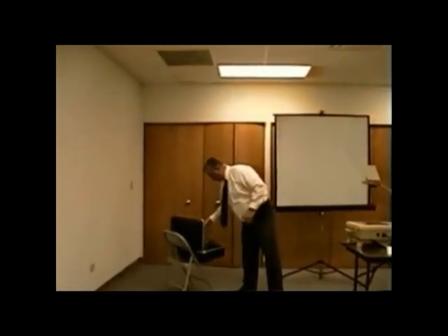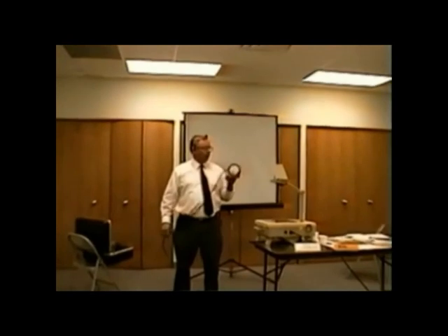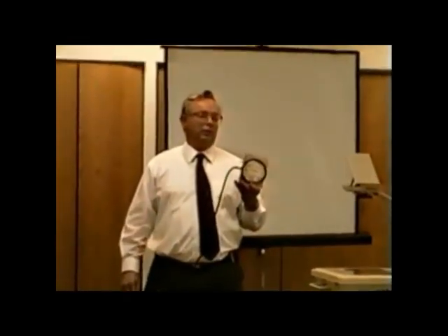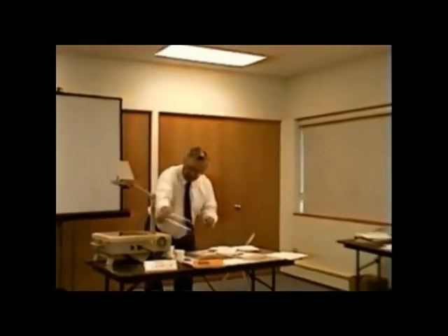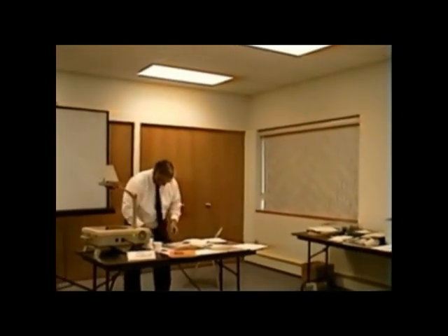If you know how negative pressure works and these switches work, you can check a pressure switch in moments. How long does it take for the inducer to come up to speed? Tee it in, flip your switch, call for heat, the inducer comes on, and in 3 seconds you've got your negative reading. The only question about checking a negative pressure, from a technician, is: I don't have one of those instruments. I don't know what these cost. They might cost $75. It's an instrument that you absolutely have to have. Okay? So is it clear now how the pressure switches work? And again, if you're not real clear, you can reread that paragraph and let's go on.